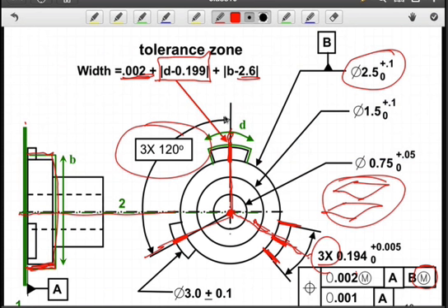Now I can compare the location of the midplane by taking the mating envelope, determine the actual midplane, and see if it falls between each set of 2 parallel planes. Note again, we are fixed with the pattern locating tolerance zone at that point.